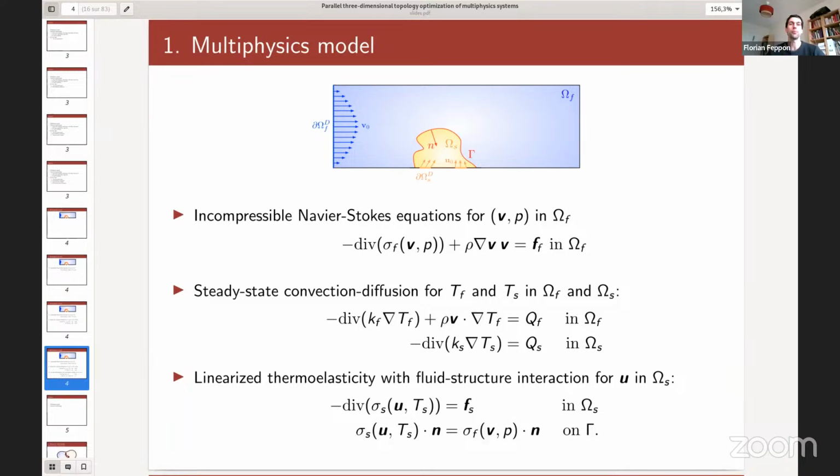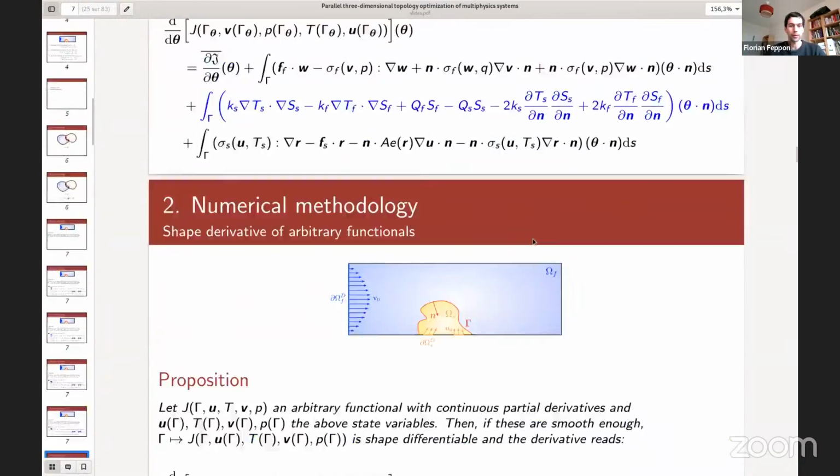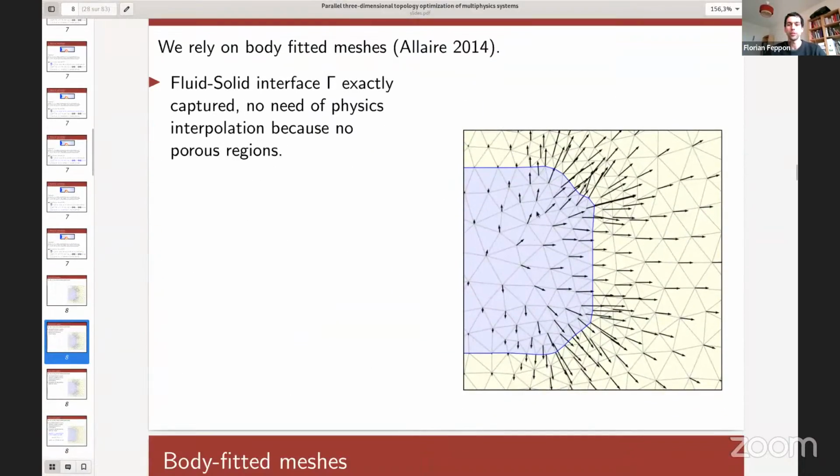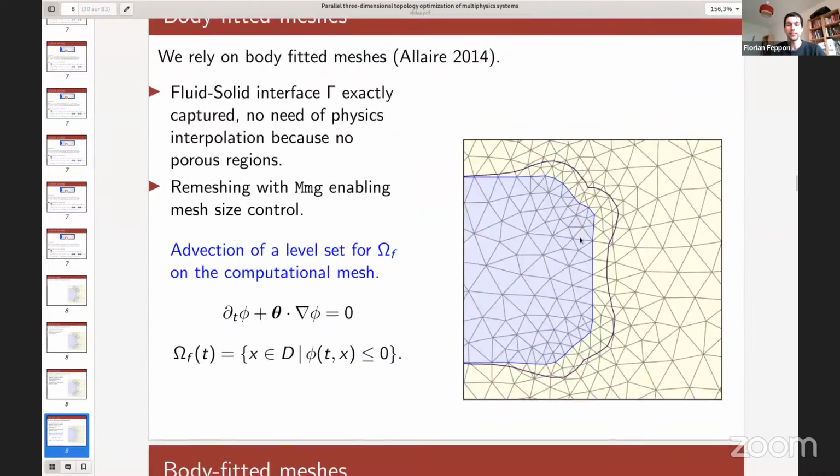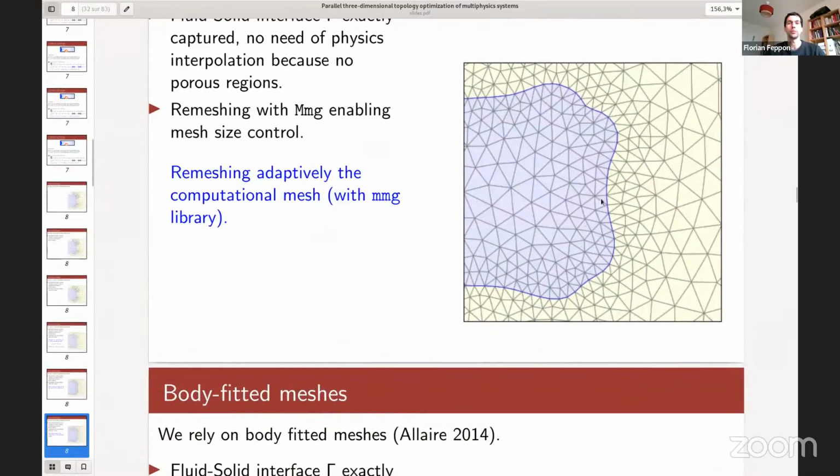So then we update the boundaries and we get a new mesh, but there is no need of any mapping between the mesh at iteration n and the one at iteration n+1. So you deform the mesh. It's not remeshing, it's mesh deformation? I say it's an abuse of language. We remesh, but it's really this picture in my presentation where we have a body fitted mesh, then we compute this level set, and then we remesh and we get this new mesh.